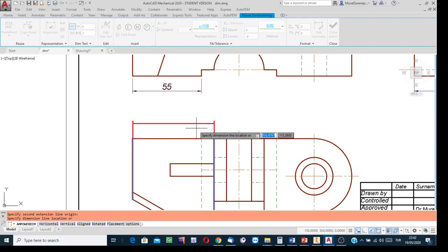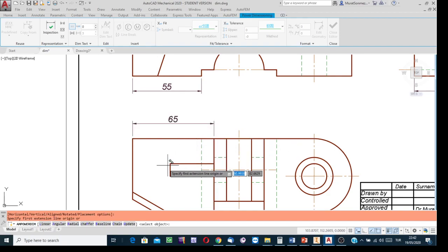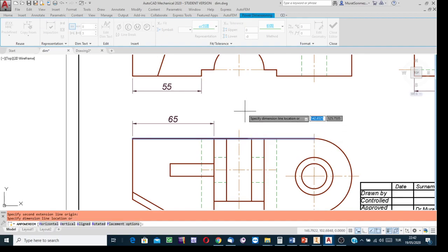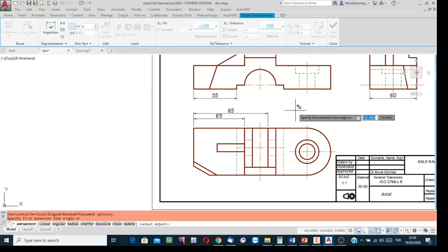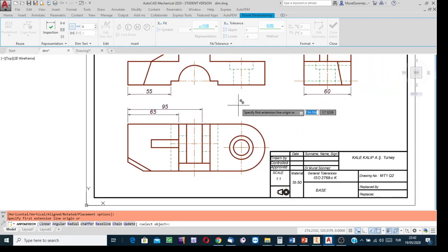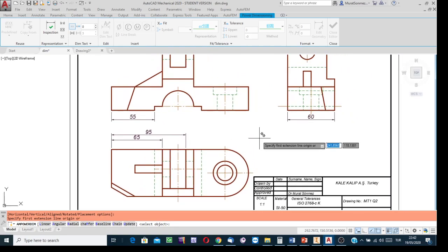Move the cursor away, 10 mm. And then for the location dimension with respect to this datum, I'm going to use not chain dimensioning but datum dimensioning for indicating the location dimension for the other semi-cylindrical extension. Well, located over here, 95. And if you have some others, then continue showing. And then press the escape button.